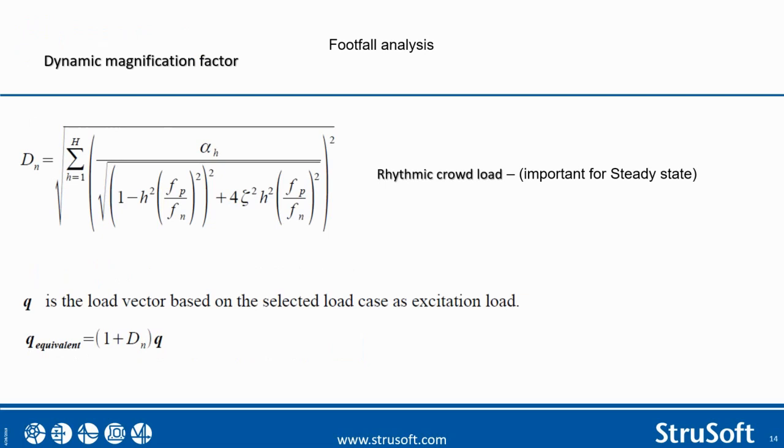Another useful result is the dynamic magnification factor for displacement. The static deflection under this equivalent static load will be equal to the maximum displacement of the dynamic behavior of the structure under the rhythmic crowd load. This result is only provided for the excitation method known as rhythmic crowd load.